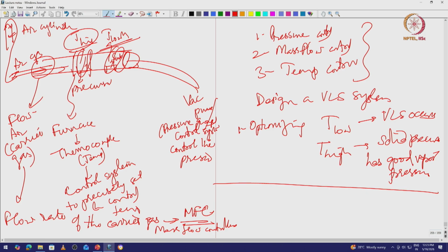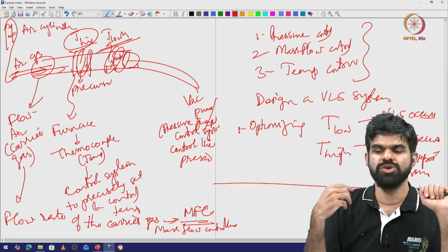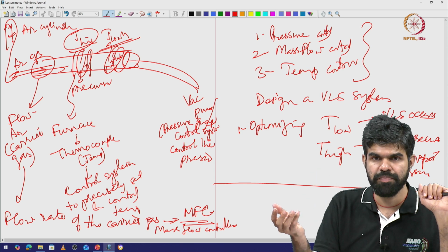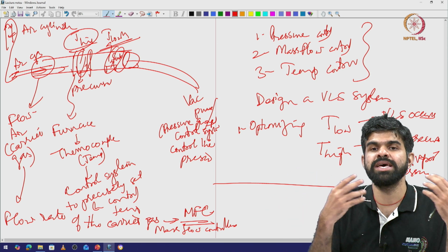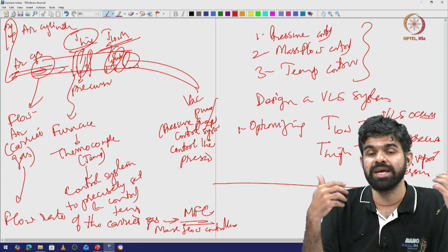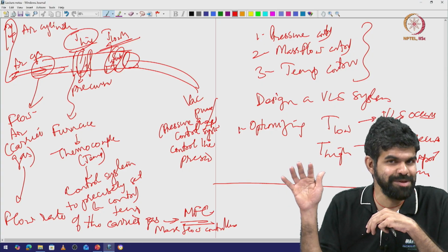So this is a case study that clearly illustrates how a eutectic is useful, right. And you can design a simple process, right. In the furnace that you have in the lab, if you have a mass flow controller, a pressure controller, and of course with the furnace comes the temperature control, you can do this process at a fixed temperature of the substrate and a fixed temperature of the precursor, and then what results are actually nanowires, right.